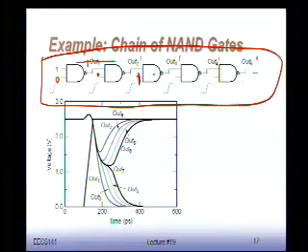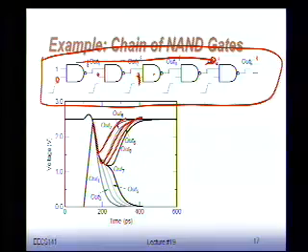But then these changes start to ripple through the network, slowly but surely, and say, hey, no, it's not the way. Actually, the input is different. So some of the nodes start to go back up. They change their mind. And the deeper you go into the chain, the more the glitching effect becomes, because it has more time to propagate through the system. Okay? So glitching is purely a result of the fact that you have long chains. If you look at this gate here, one input is a primary input, changed at the time of the clock. The other input has to propagate through a long, long chain.